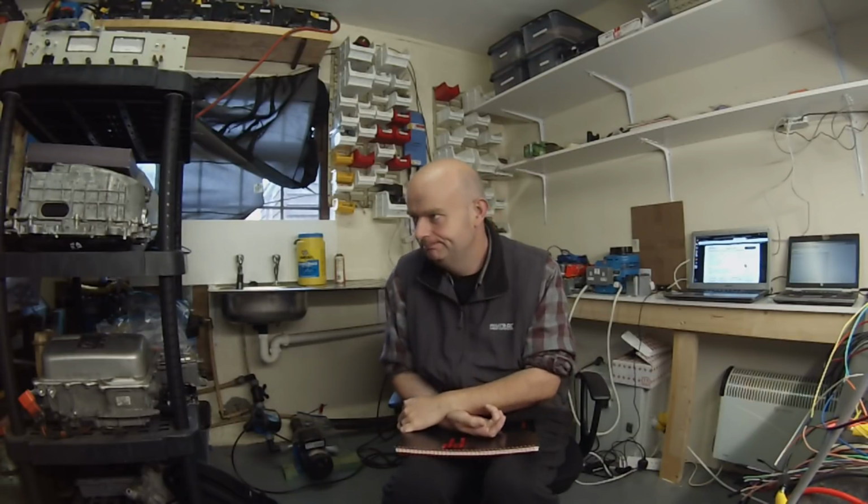Set the current limit to 5,000 amps. Same again. 900 amps. Shut down. Set the current limit to 50,000 amps. You guessed it. 900 amps. Shut down. Set it to 65,535 amps. 900 amps. Shut down. We've got our real problem.